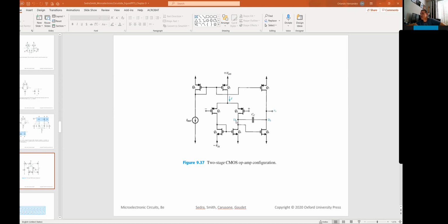Hopefully we can get to it. I'm not sure. But we'll talk a lot more about that capacitor in that chapter if we get to it. If not, then at least you sort of know why it's there. But it's necessary to make the circuit stable, and it's always there in op-amps. And it sets the gain bandwidth product or the pole of the op-amp.